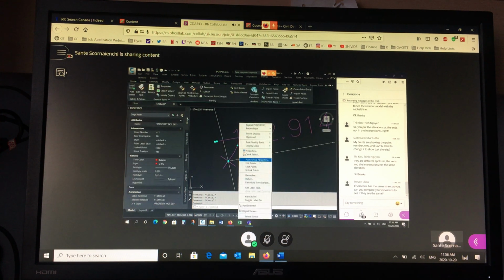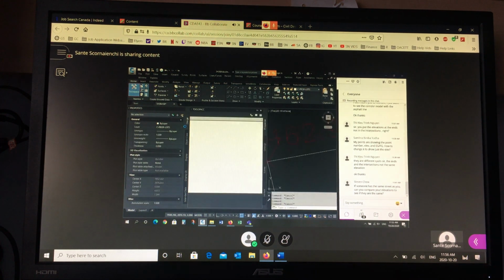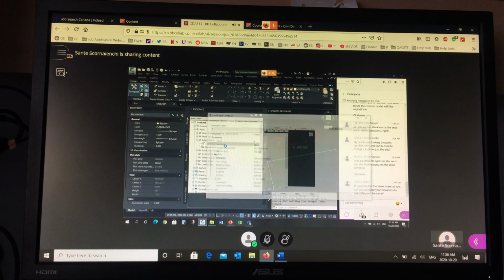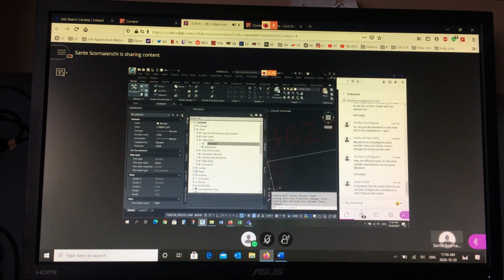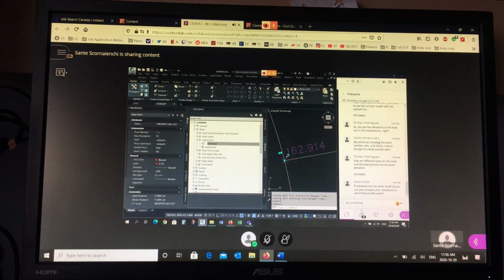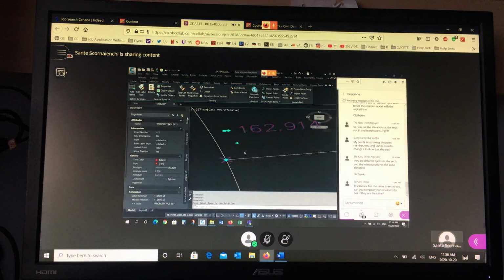If you don't want to see the leader, then you can go to the style for the marker. So if you go to the label style, which is in the settings, under label styles, you're going to have a different name, obviously. If you go to the dragged state, you want to make sure that your leader is false, off, and as composed. Right? So if you don't want to see your leader, which you probably won't, this is how you turn it off. It's in the dragged state, and then your leader should disappear. Right? So now if you drag this away, there's no leader. There's no leader visible.